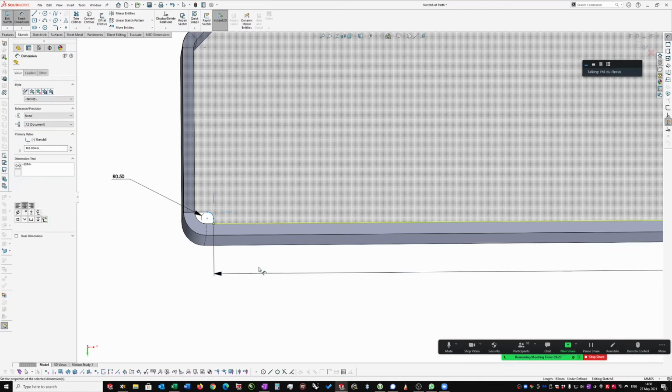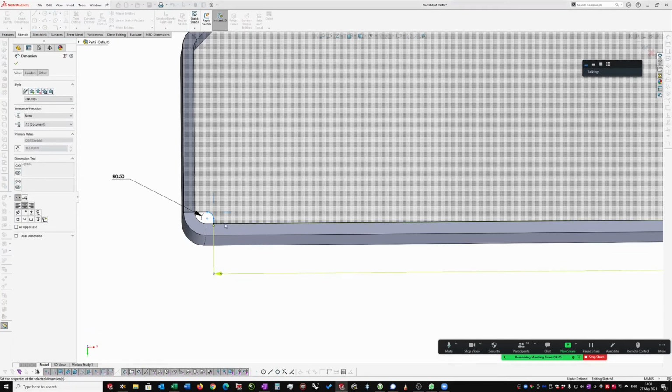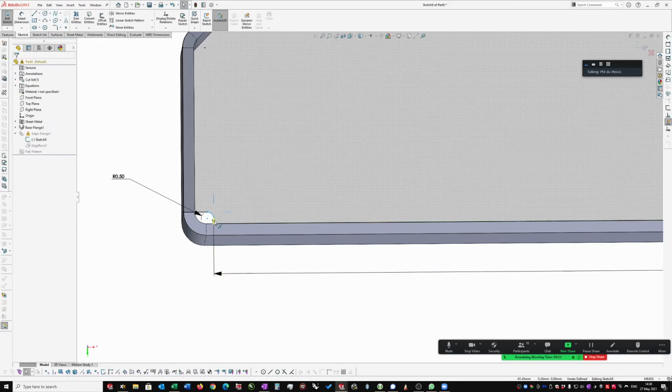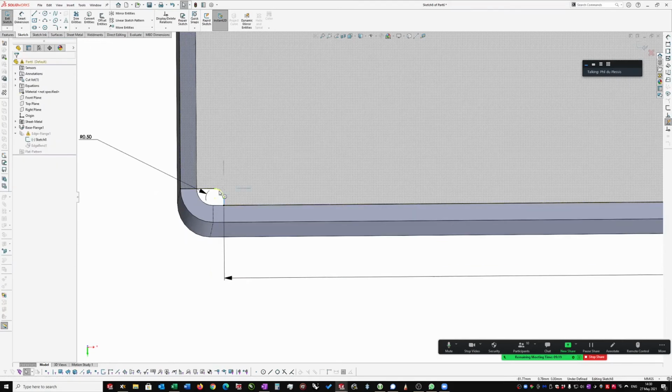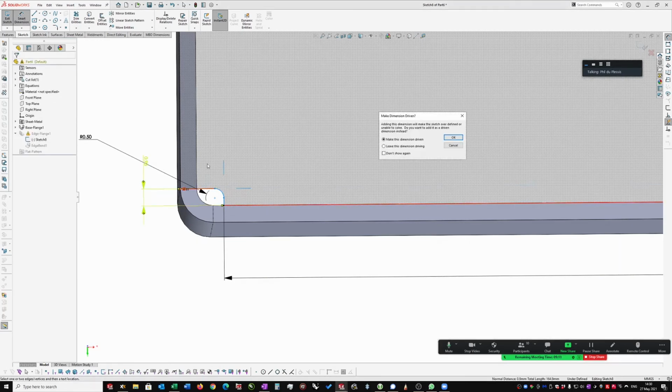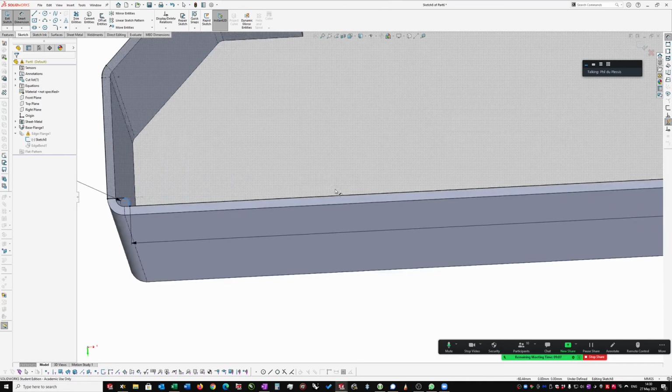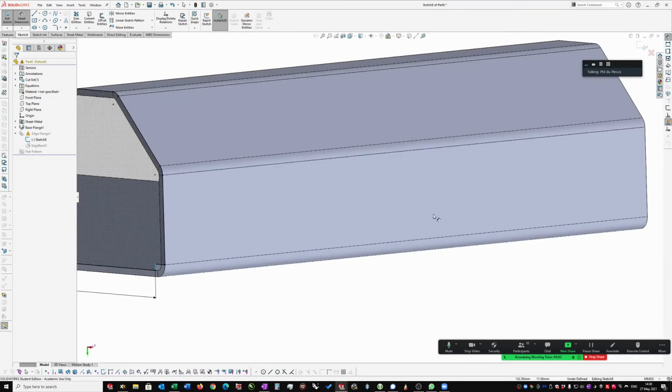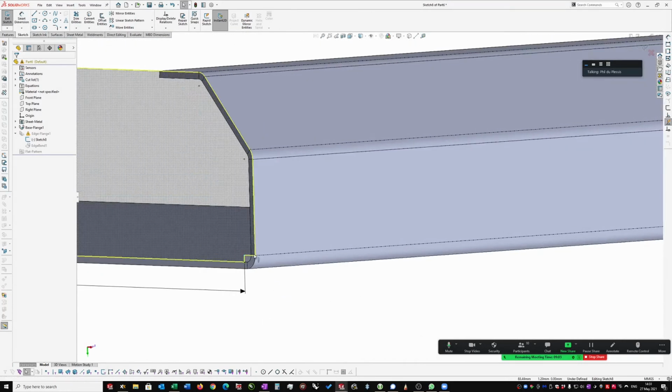That dimension back. And I'm not sure why this is not... might be a height thing. Let's just see. I'll put that in. Pretty sure this is going to say I'm over defining. Yes, over defining, because that line there is already connected on this side. Here it's already connected to that piece there. So it's just a matter of this little piece here.